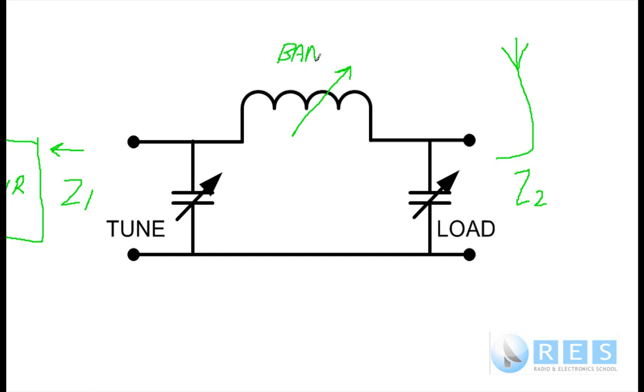So you might have the 10 meter band, the 20 meter band, you might have those switches on it. But basically the antenna tuner is just adjusted. You adjust each control, each capacitor, until you get minimum SWR. And really with an antenna tuner you can adjust it to get an SWR which is 1:1. It's quite easy.